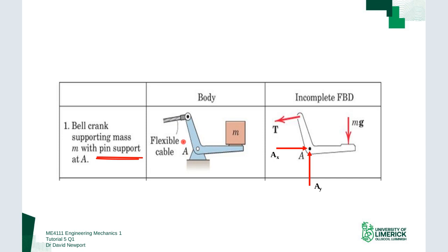So if I look at just this pin joint, what I do is I cut it here and I cut it there, and I forget about the cable up there, I forget the mass here. And I take this object, and if it is just here at point A, and there's no forces up there, no forces there, and I try and push it in the X direction, it's going to push back, it's going to try and stop that. And if I try and pull it up in the Y direction or push it down in the Y direction, it's going to react. So I can have reaction forces that are in either of these directions. I'll come back to how I decide the direction in a while.